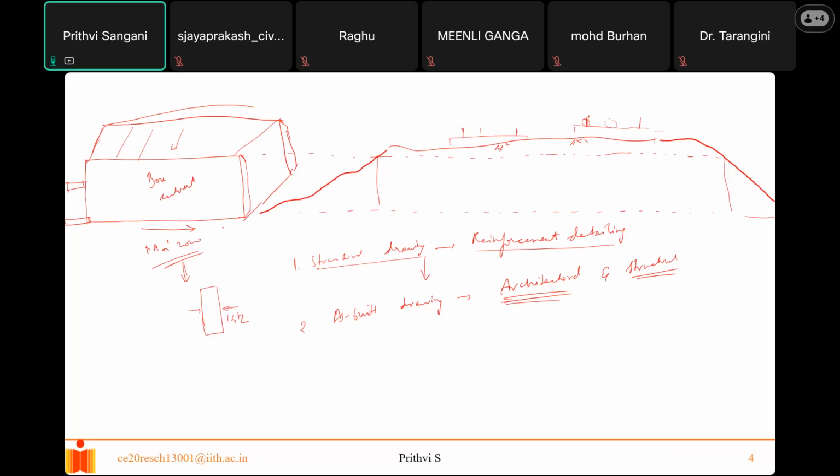So the engineer in charge, who was supervising this task, has lost these as-built structural drawings. Now they are not sure what kind of reinforcement went into these box culverts, and they had issues pushing this in under the railway, because, as you know, railways have no margin of error in terms of safety. So they are still in doubt whether they can push this, or whether it can sustain those railway loads or not.